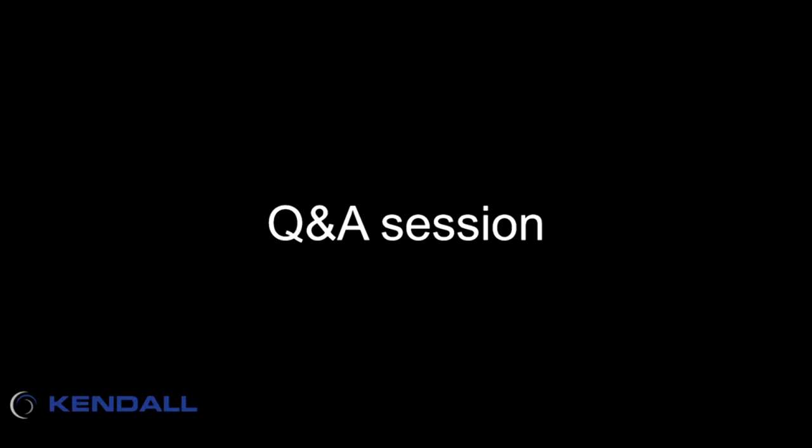So good question. Okay, so if I'm understanding correctly, if you have a Tech Connect contract, RSLogix 500 version 12, which is the version you'll need to do an ACD file, should be free for you to download. Yes, sir. If you own an older version of RSLogix 500, that is correct. If you do not own the software at all, you'll need it to convert. And if you're in a pinch, you can possibly have one of our automation engineers convert the file for you. So it's just a one and done type thing.